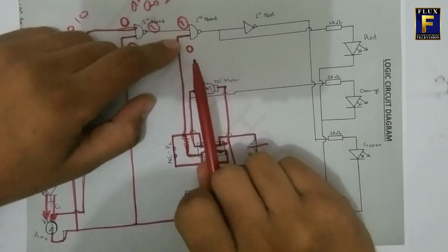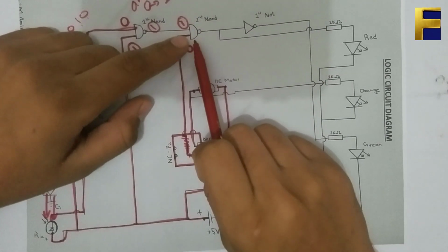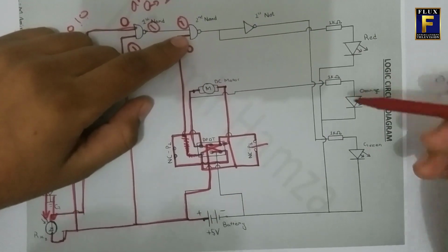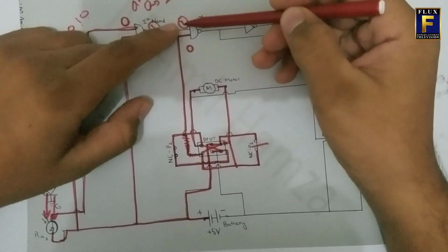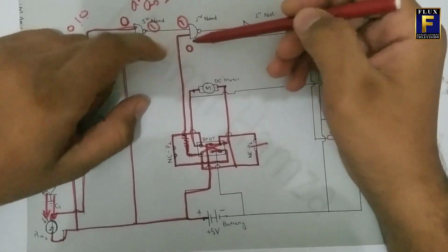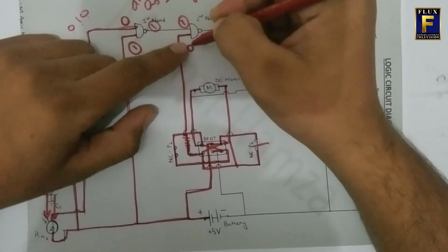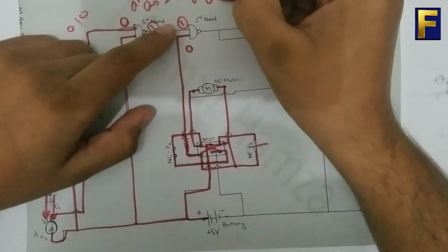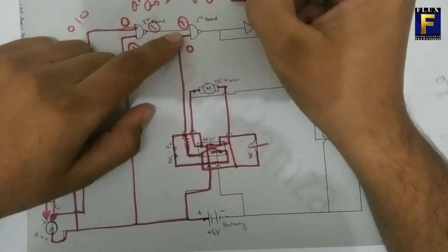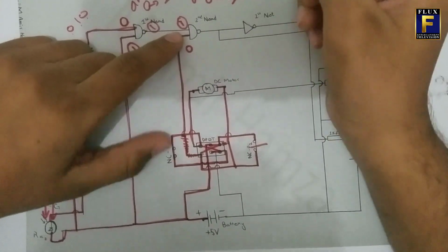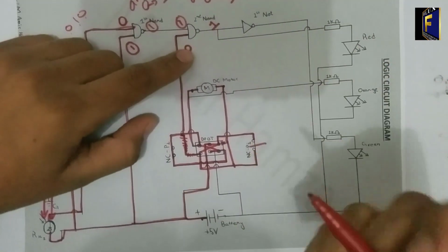Now what will happen, as I told you before, the second NAND gate is playing the role to operate the LEDs. So the operate LEDs is now getting 1 at the first terminal and 0 at the second terminal. And again in the AND gate, if you're getting 0 and 1, it's 0, but as it has the NOT on the top, it will convert that 0 into 1, meaning that we start getting 1 as the output from the second AND gate.